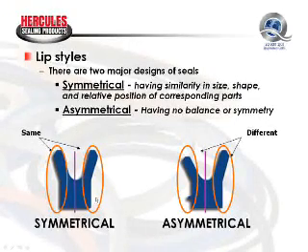The advantage to the symmetrical is that it can be used either as a rod seal or a piston seal. The advantage to the asymmetrical is that it works better in a dynamic low pressure sealing application.